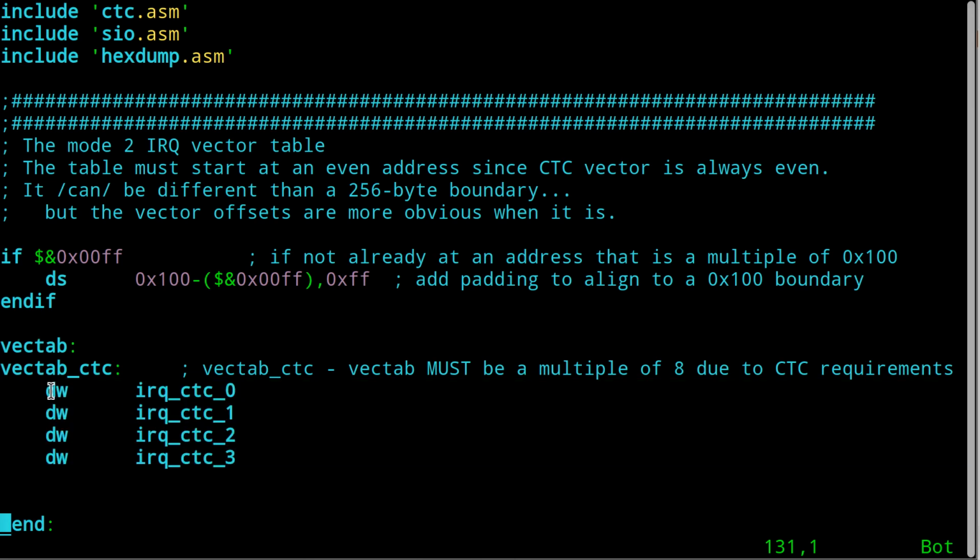Then what I would know is that the beginning vector number of this first one here would be at the address of this label minus the address of that label. Because there's nothing between these two, it'll turn out to be 0, which is exactly what it should be in this particular example. Okay? But I'm giving you a general purpose sort of thing. Again, it's going to be more flexible if you want to reuse it in other scenarios.